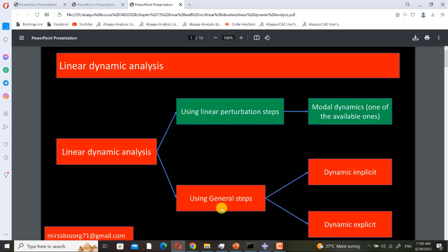In chapter 7, we did a simulation for a structure. It was a plate with stiffeners, and a blast load was applied to the plate. And we used a dynamic explicit step, and we defined plasticity, and also energy was set to on. It was a nonlinear dynamic analysis.